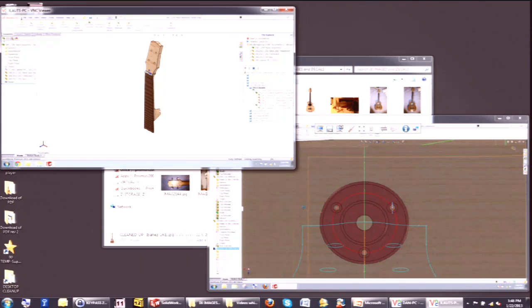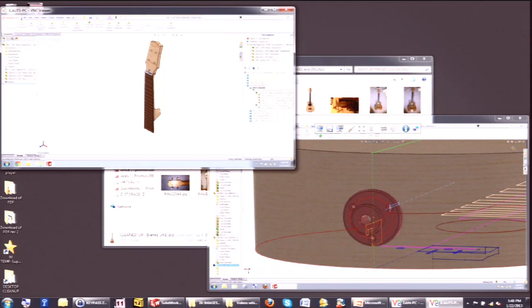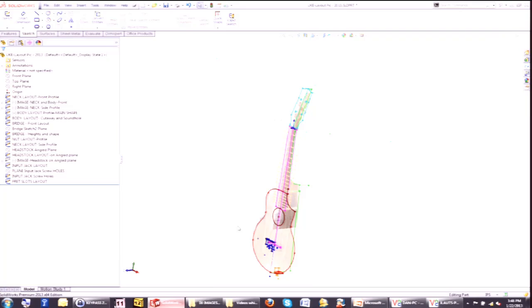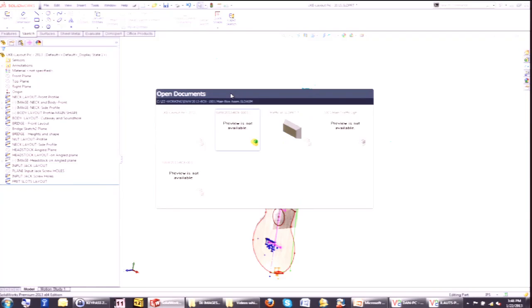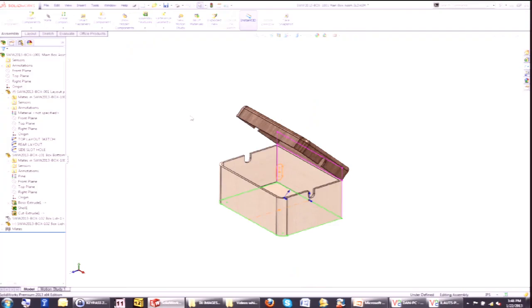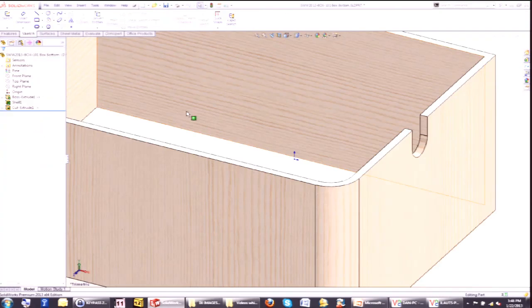Another question: when you did the dual lids and you dragged another one in and excluded it from the BOM, the mass properties are still going to show too, though. That's an excellent and legitimate concern. Here's a different approach. You could just make a new assembly.